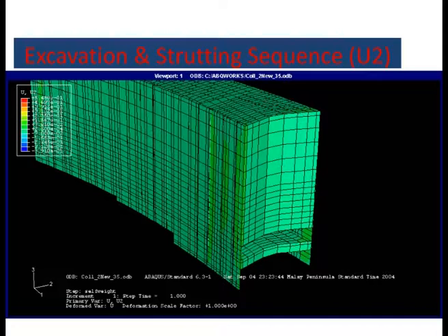So, basically, we model layer by layer, layer by layer, until the 10th layer. Then we start to go left. At the 10th layer, our excavation went from here down up to here, and then it sort of proceeded from the east to the west. This is the east direction. This is the west, so the excavation proceeds. We model the excavation in detail on the 10th excavation.